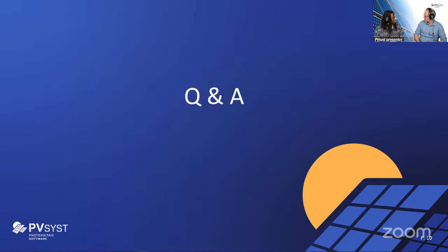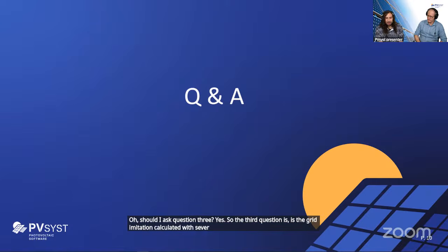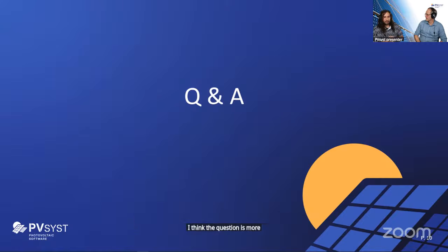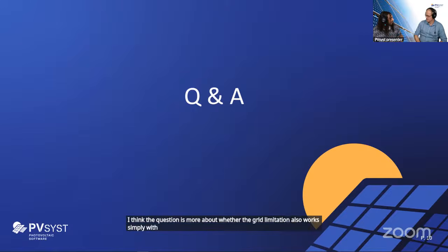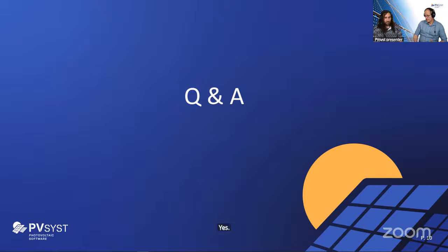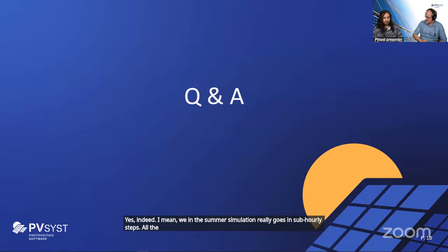Should I ask question 3? Yes. So the third question is: is the grid limitation calculated with sub-hourly timestamp if you're doing a sub-hourly simulation, or is this loss always only showing at inverter level? I think the question is more about whether the grid limitation also works simply with sub-hourly simulation. Yes, indeed. I mean, the sub-hourly simulation really goes in sub-hourly steps. All the simulation stages that we do in hourly simulations, we do equally in sub-hourly steps.